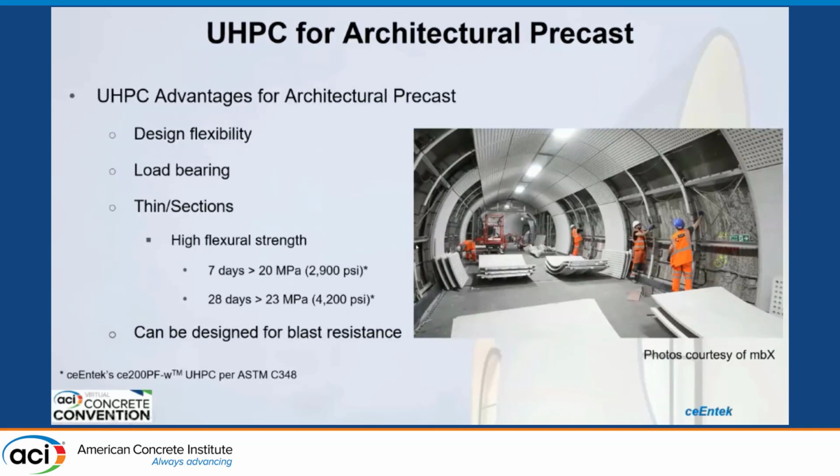One of the things that architects really like about this, you can see these are precast panels. That's a very popular application for architectural UHPC. You can see how thin this panel is. They've got these ribs that stiffen up the section and make it a little bit easier to make sure that you don't have to worry about the thing flexing or otherwise developing any cracks. Obviously, like we talked about, this material would hold together. You wouldn't have to worry about it falling apart or anything like that. But you still may have a crack if you warp it too severely.